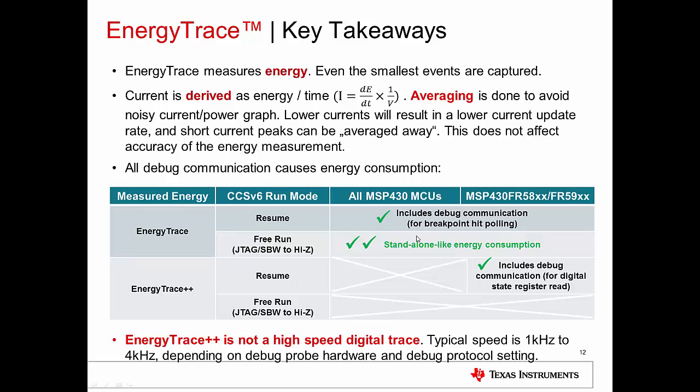Last but not least, I wanted to have one more key takeaway for everyone here, which is that EnergyTrace++ is not a high-speed digital trace. Typical speed is between 1 kilohertz to 4 kilohertz, depending on the debug probe hardware and the debug protocol settings also.